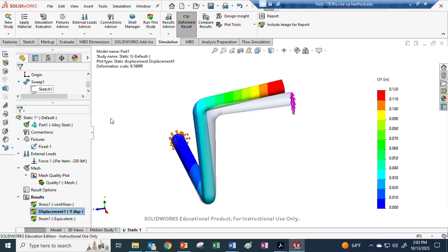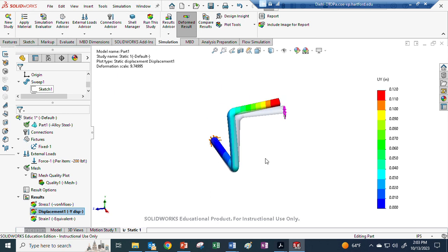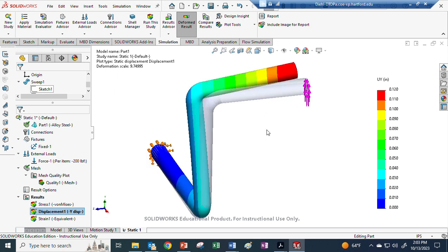One of the quirks of SolidWorks Simulation is that when you grab a number off of that plot tool setting, it uses the same number of decimal places as you choose right there, and we would rather have at least 3 decimal places, just to have enough sig figs.